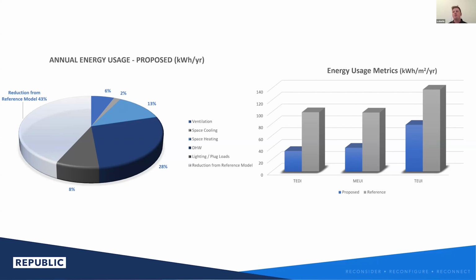But we've really reduced the amount of space heating and space cooling energy we can by tuning the building envelope in this case to find almost that point of diminishing returns in terms of how much insulation you really get the value of in your roof, how much insulation you can provide on the wall, and really make sure that you're getting the full benefit of it.